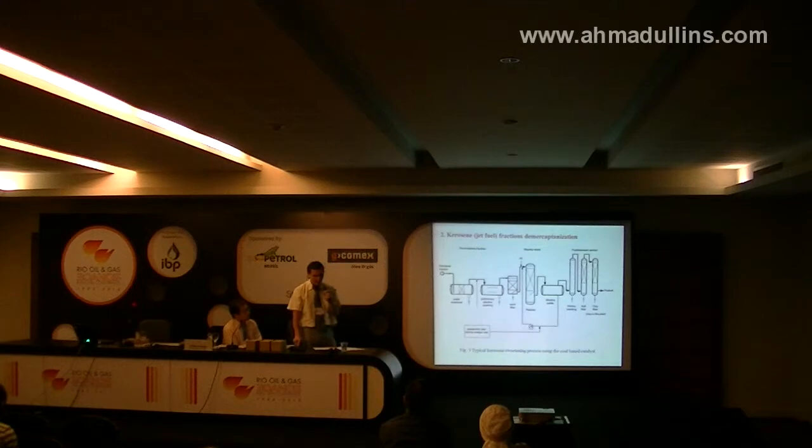To involve the entire volume of virgin kerosene in the composite jet fuel, it is needed to sweeten it from mercaptan sulfur content, which is from 4 to 10 times higher than normal acceptable for jet fuel, 30 ppm weight. In this context, the process of selective oxidation of corrosive mercaptans into inner disulfide in an alkaline medium at 40–60 degrees Celsius becomes relevant. Estimated capital cost for hydrotreatment of kerosene compared with alkaline sweetening is higher from 10 to 20 times and operating cost from 20 to 50 times.